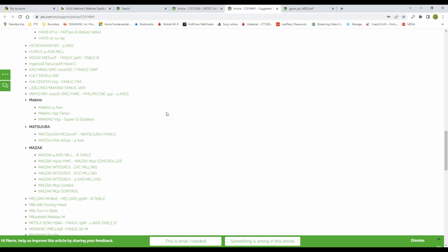If somebody else started with it, you don't know all the variables. You need to go and double check that. So just be wary when you use these. And like I said, they're not machine ready. Don't go and generate code, put them on your CNC machine. You'll most probably end up gouging parts or damaging your machine.